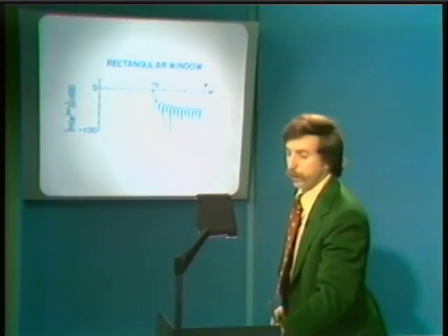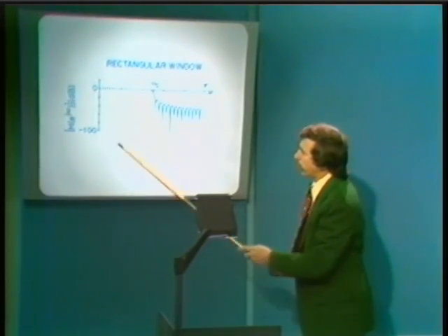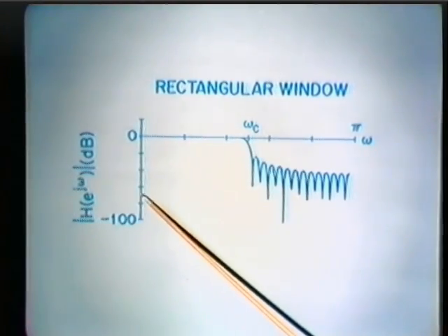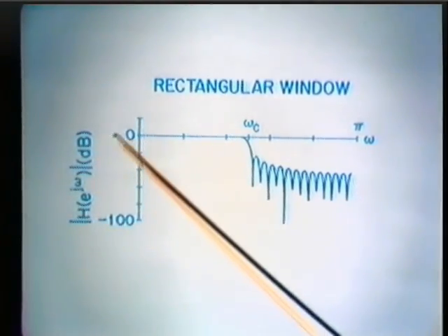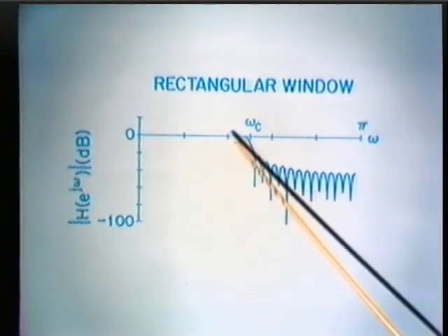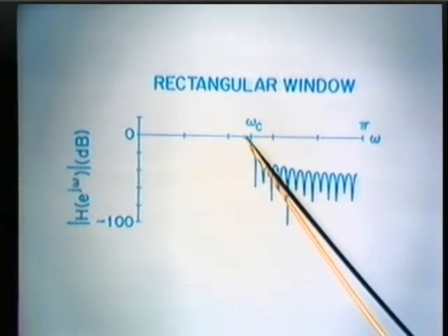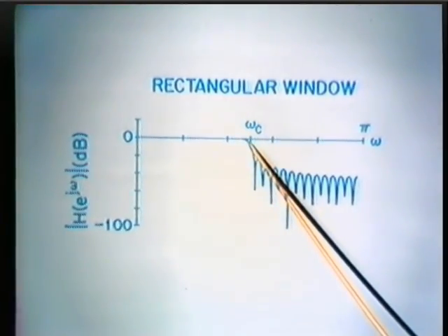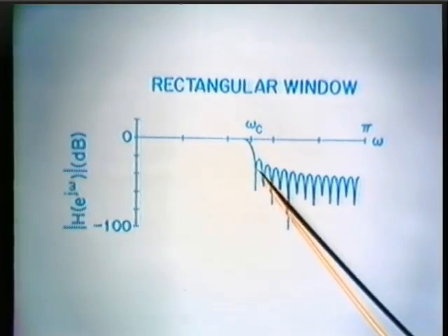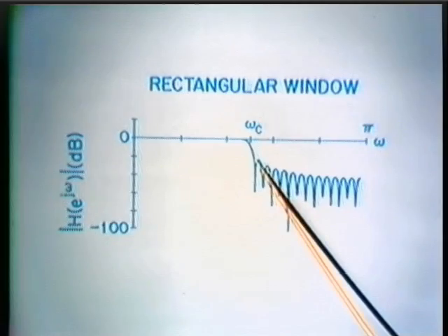The resulting frequency response for this particular example I've indicated here, and as opposed to one of the previous frequency responses that I depicted, this is shown on a logarithmic frequency scale. There, in fact, is some ripple in the passband, although it's not evident on a logarithmic frequency scale. But generally, you can see the effect of a transition band and then a side lobe structure in the stop band.